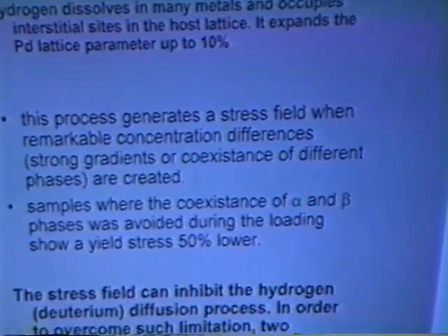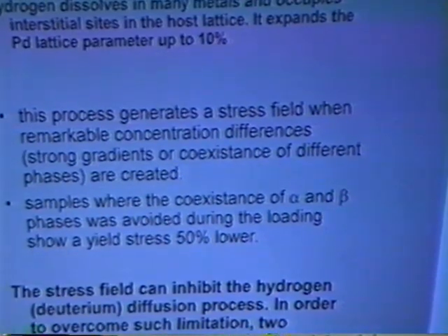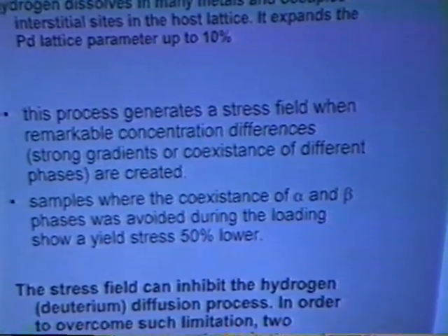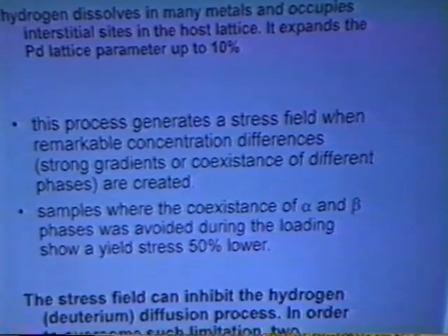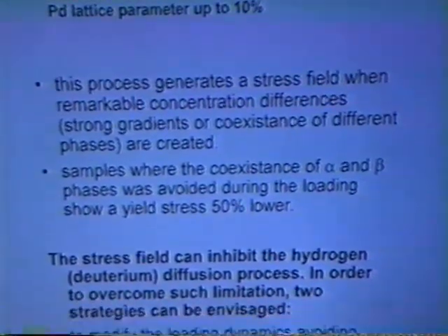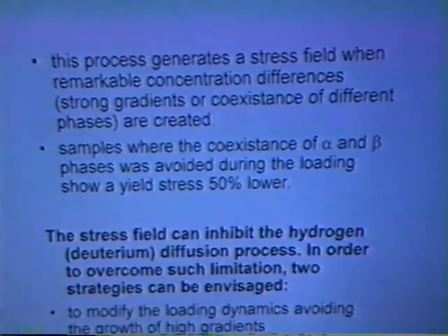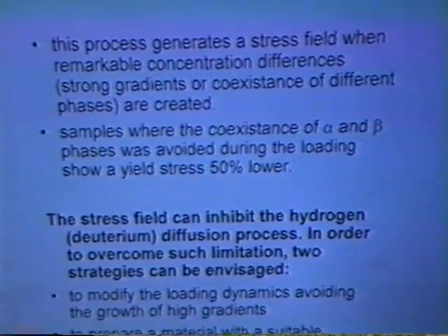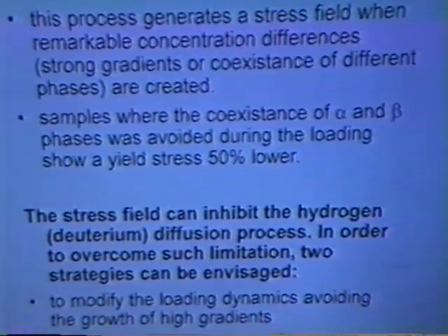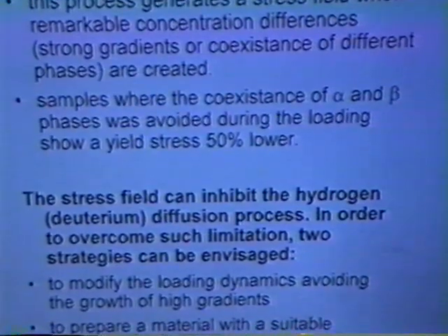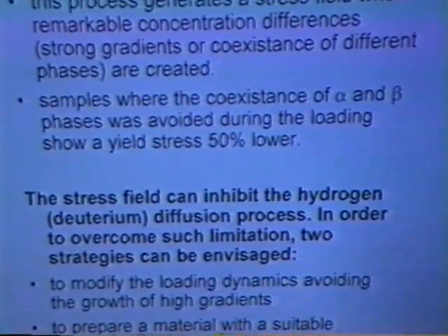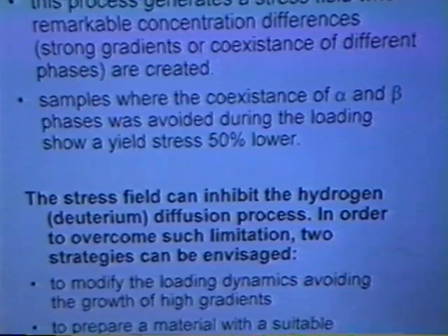This process generates very high stress fields when there are remarkable gradients inside the metal. And because the diffusion coefficient is very low in palladium, every time that you try to load hydrogen in palladium, you have a very high concentration gradient inside, and then a very high stress field.